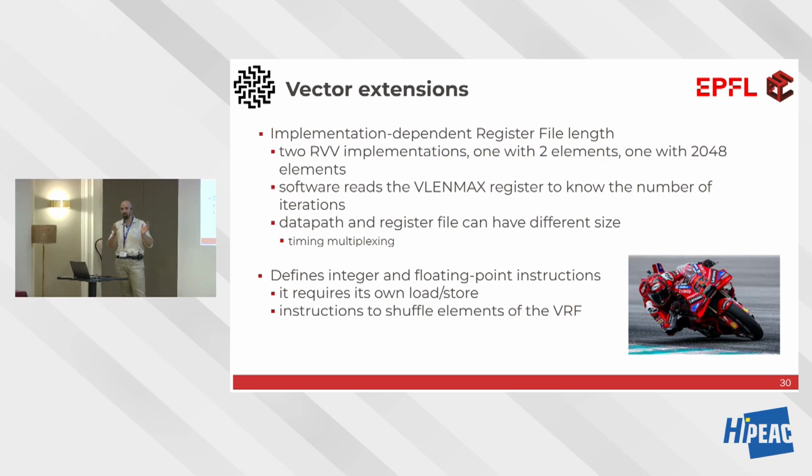We said that till now. If you compile something with one code, that's the main difference between non-vector, like pure SIMD machines, where the length is embedded in the instructions, and vectors. In vector code, the code itself reads these registers and iterates over the application's number of elements divided by the physical register size. So for example, if you have 4 elements, but your application requires 10 elements, then you do one iteration with 4, another iteration with 4, and then with 2. If your CPU implements 16 elements, it's done in one iteration.